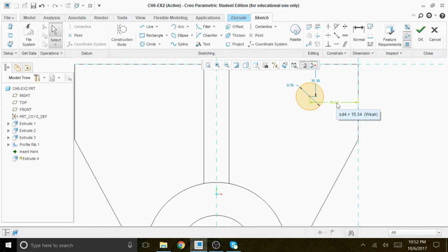In SolidWorks, it's the same thing, but they don't really show any numbers or dimension. They just tell you that your sketch is not fully defined and you have to give enough relations or constraints. You have to impose constraints; in SolidWorks, they call it relations, okay? Like adding necessary dimensions, or using tangent, or symmetric, or coincident, and so on, okay? Let's continue. All right, I'm going to give the dimension here, called 18.